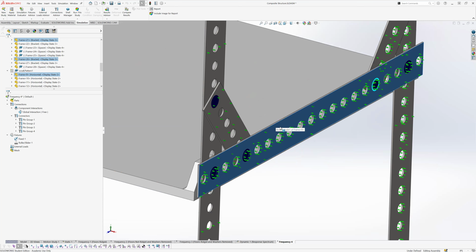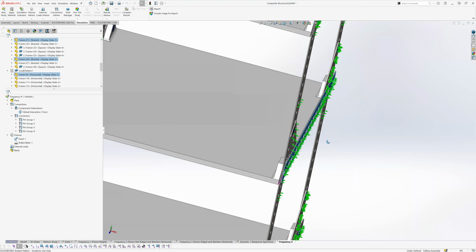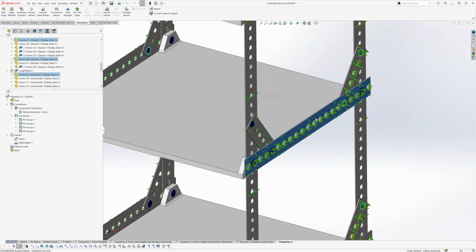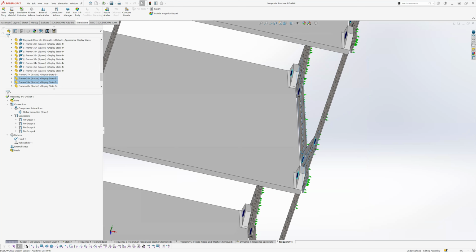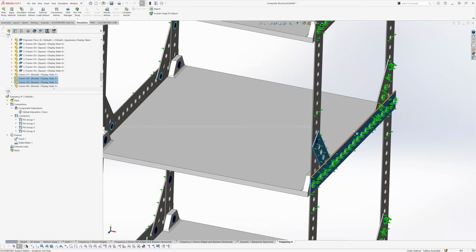Another reason for not putting them on the inside: if I were to put a roller slider on both sides, as this member were to deflect or vibrate or whatever, what would end up happening is the thickness of the member would not actually be able to change because of that roller slider, because this face cannot move off plane and the inside face cannot move off plane. That's the issue with that.